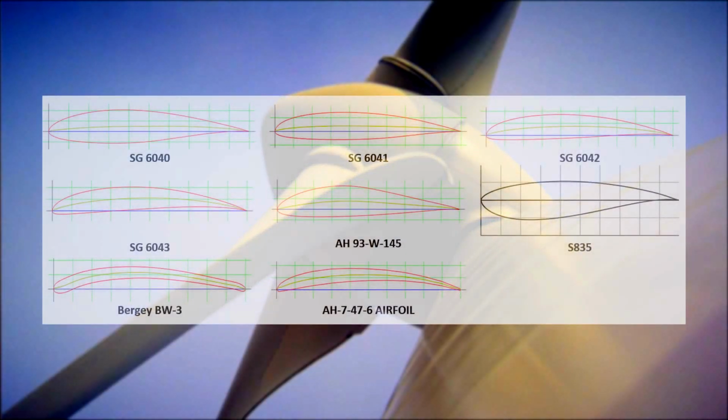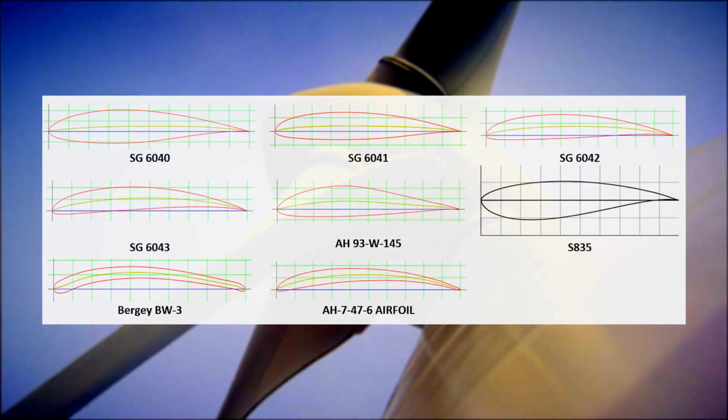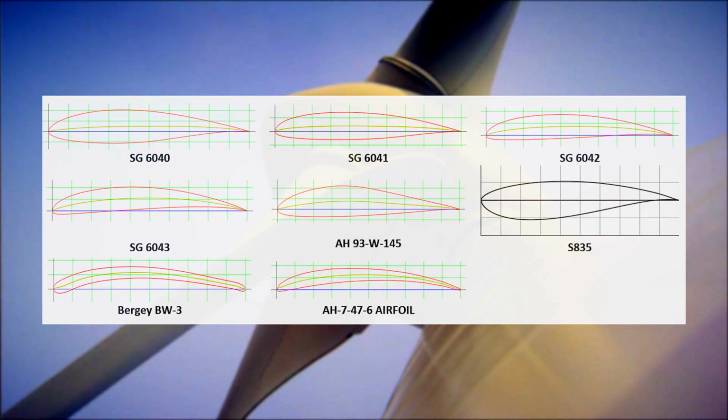We compare the aerofoils by looking at their CLmax, CL/CD ratio, and blade aerofoil geometry. It is necessary to choose an aerofoil with a high CL/CD ratio to maximize rotor torque. Our initial shortlist was these 7 aerofoils. We eliminated aerofoils because their CLmax requires high angles of attack, which is not feasible for our turbine design.